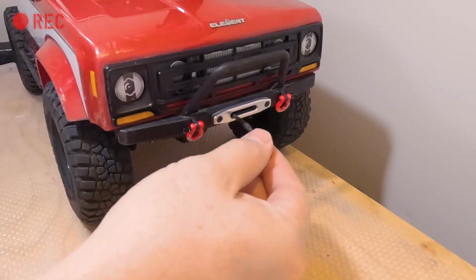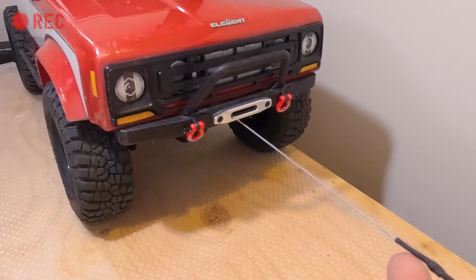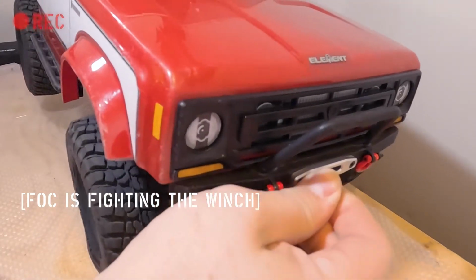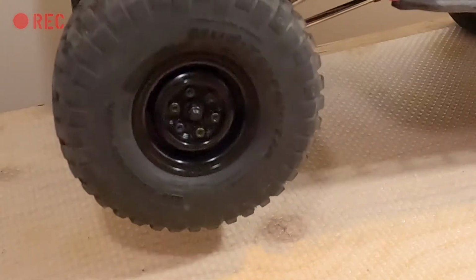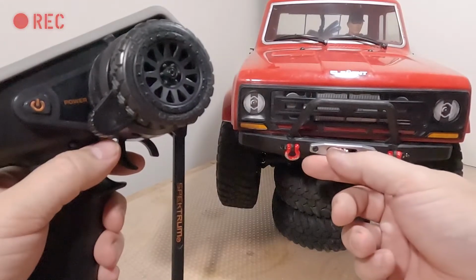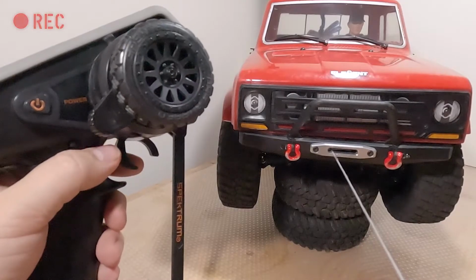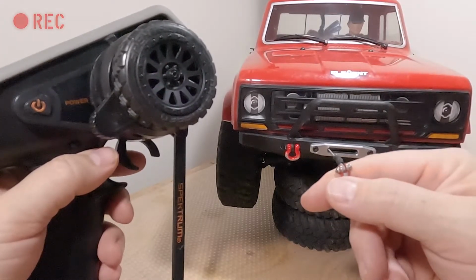With winch priority channel mixing active, when you spool your winch in or out, your truck will also automatically drive forward or in reverse at the rate we specify. This way, you're not required to actively match your throttle speed to the winch speed, giving you one less thing to think about. I'm going to demonstrate this setup with the Spektrum DX5 Rugged radio, but the concept should be applicable to any advanced radio system with at least one auxiliary channel.